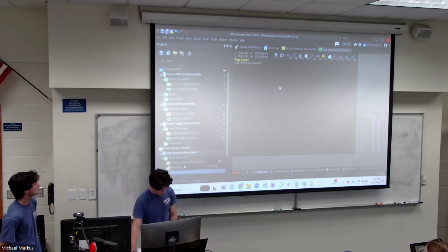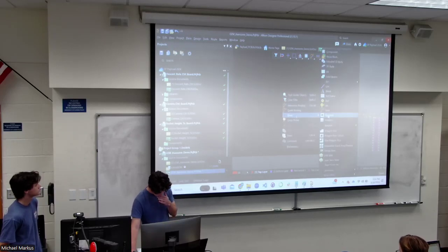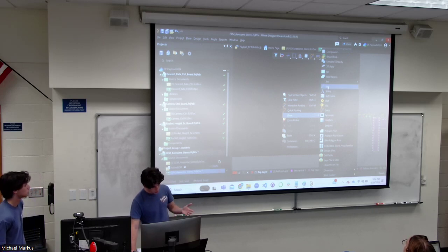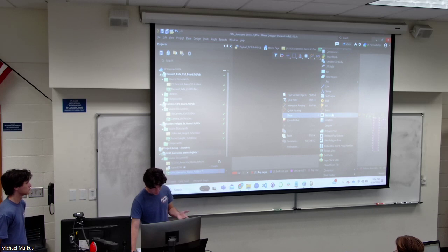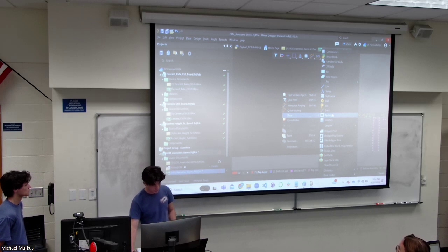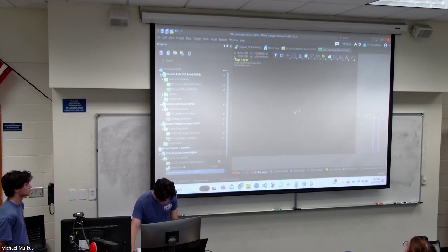So what we can do is you can either come up to place, or I prefer just right clicking, place. You can either place lines and define a custom shape, or you can place rectangles. You can also do squiggly lines and circles and stuff to define your board shape. I don't know how many manufacturers are able to do that, but you can. But the easiest thing to do is click place rectangle.